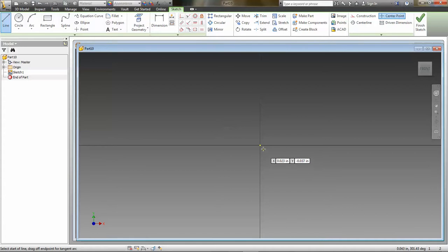So we'll go to the XY origin, and 0, 0 is our origin. We click there. Then the part goes over 1/4 of an inch to the right, so I'm going to literally type that in, 0.25, and 0 degrees. As soon as I can see that it's the right dimension, I click there. Then notice it's got the dimension in there, and the line is purple, indicating it's constrained. Then I go to the next point and type in my 0.25 dimension for that. Click there. We go to the right, 1.5 inches at 90 degrees.